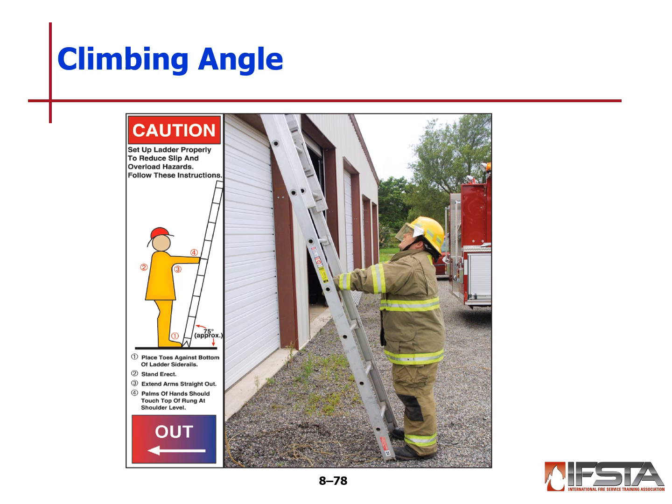We also have the nice pictogram sticker on the beams of the ladders these days. It has an arrow telling you which direction to pull the ladder out, and it also gives you the key points: you want your feet up against the beam, your arms outstretched straight out, and you're touching a beam that gives you that proper climbing angle. So you can quickly do that without doing math in your head.